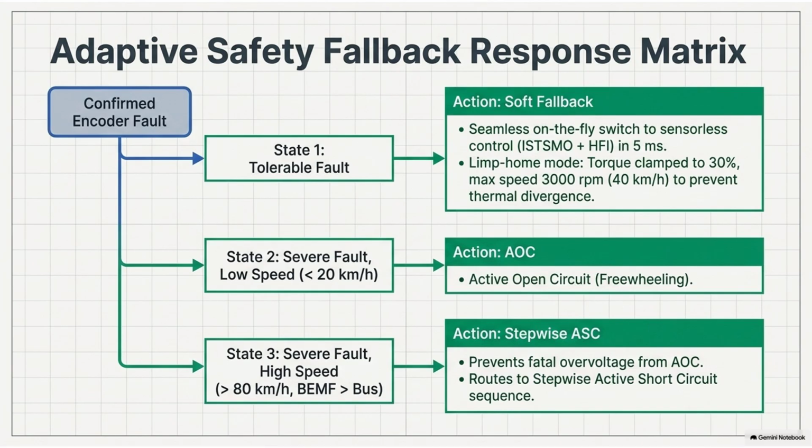And, on top of that, that specific material has zero piezoelectric effect. Right, because certain ceramic capacitors exhibit piezoelectricity, meaning if you physically vibrate them, the mechanical stress generates a tiny electrical voltage across the terminals. Exactly. In a vibrating car, normal capacitors act like tiny microphones.